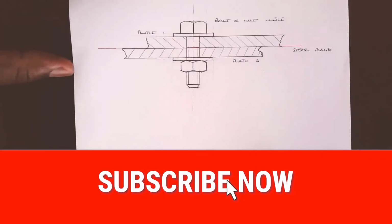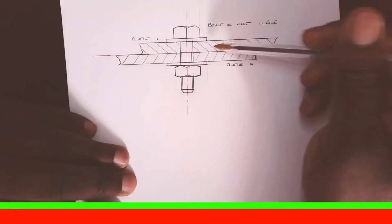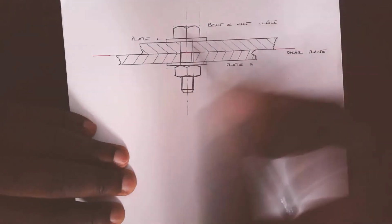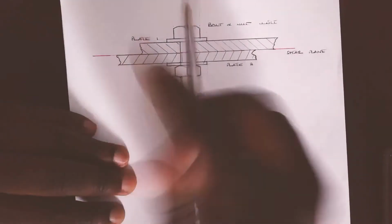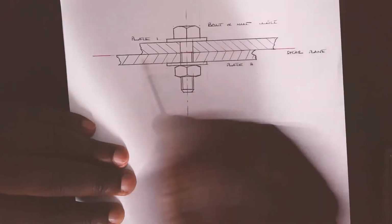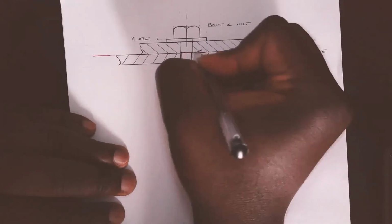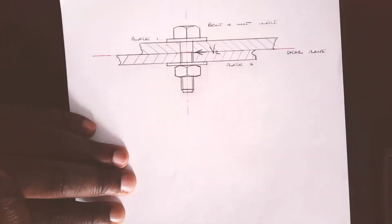Now look at this problem. I'll say work along. As stated in the question, we've got two plates, plate 1 and plate 2, clamped together by means of this fastener, a nut and bolt. As I've more or less inferred in our discussion, the interface between the two plates is going to create an axis of shear, or a shear plane. And it is along this plane that the bolt is going to experience the largest possible shear. Let's call that PR in there.